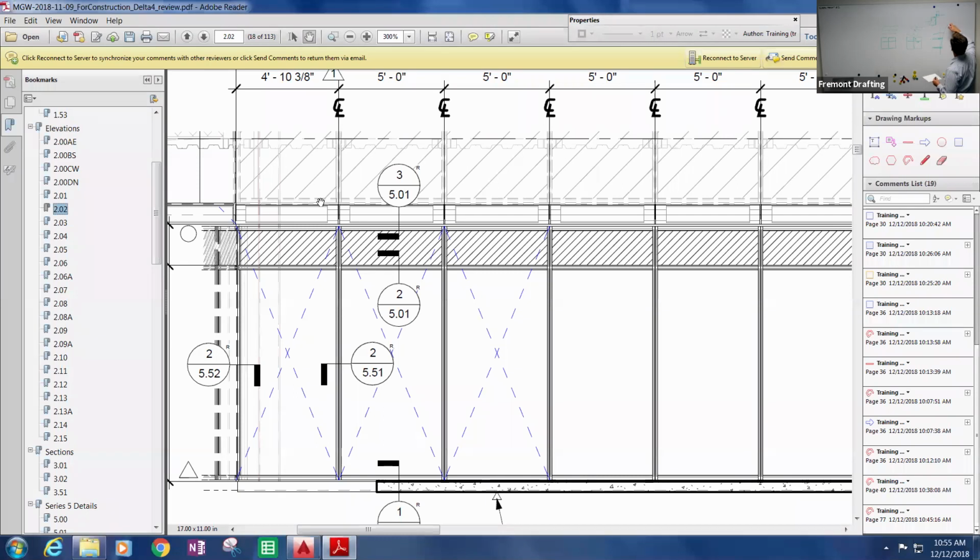So normally that detail for us would look like that, and our window would overlap it. We would have a caulk joint over here. So that's when we're moving together. And then this is racking with us, but if it's translating, this element is doing this as well, whether it's plaster or precast or whatever. As long as we're moving together, we're okay.